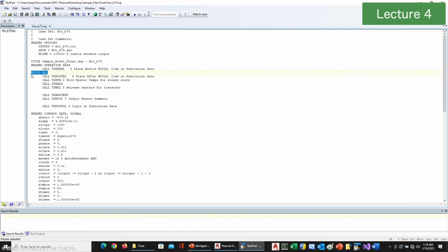So when the preprocessor sees this, it's going to expand it. What this is saying is build all of the submodels that I've defined as my solution configuration. You could alternately say build, give it the name of the solution configuration, and then separate by commas all of the submodels that you wish to build after it. So this does allow you to include things in the Cinda model, but then not include them in the solution, or start with it in the solution and then remove it afterwards.